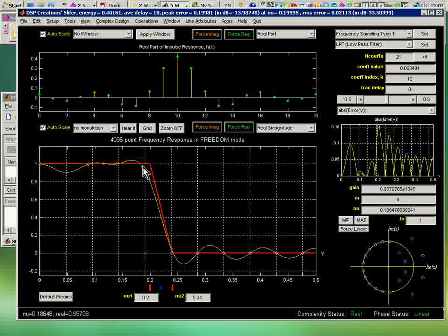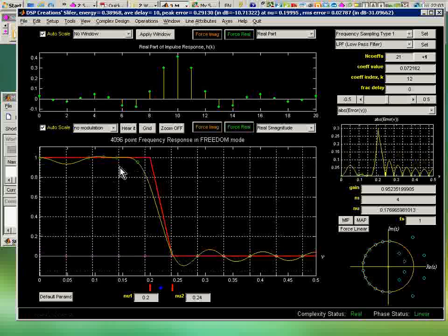Of course, I have to be careful because the design escapes elsewhere and may be quite bad if I get a very ill-conditioned Vandermonde matrix, which is guiding the inverse transformation of these samples and taking me back through inverse DFT to get through an inverse Vandermonde matrix to get my coefficients. I have, through the combination of these operations, the ability to handcraft with great flexibility and meet very difficult design requirements.